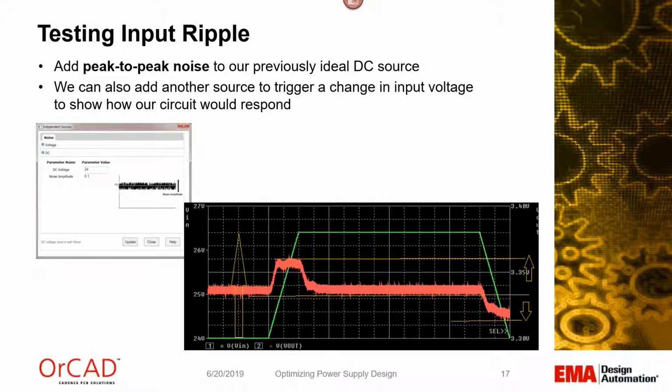Here on the bottom right, we have in orange our output voltage. In yellow, we purposely put in a spike for our input voltage, and we can see that for our circuit here, our output voltage is not knocked off. It doesn't suffer from any instability with a voltage input spike of this size. It's able to respond well and readjust to that change in the input voltage.